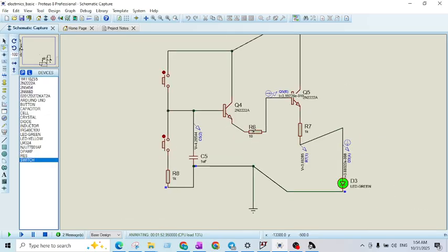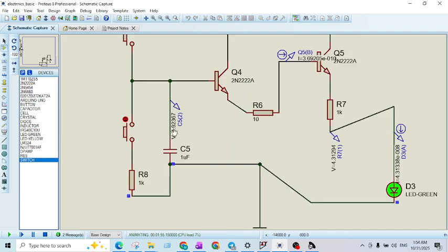Well, so if I push here, now this capacitor is discharging through this path. So here you have one base emitter terminal, you have another base emitter terminal. So you actually have two base emitter terminals and also one LED to discharge this capacitor. That means it will take a lot of time, and I measured it takes around 1 minute for this LED to turn off. But if you want this LED to turn off instantly, just press here and you see this LED is turned off.